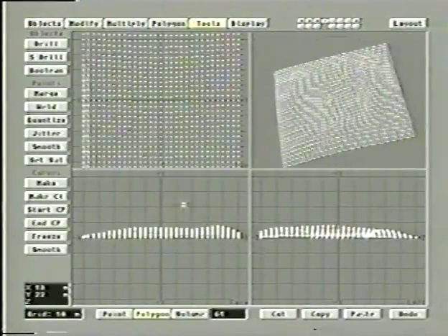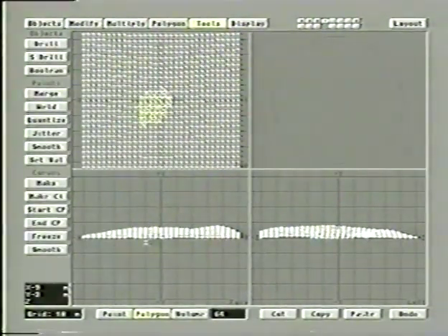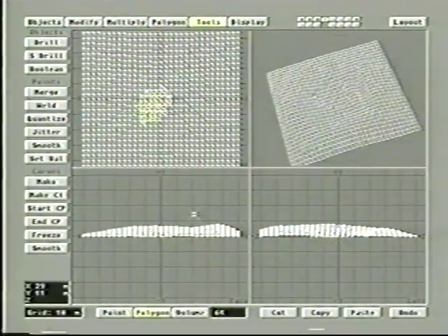By putting the ground at -1 millimeter, when the road object loads in, it will be right on top of the ground, which is quite handy because it means I don't have to push it up or anything like that. So that's all I'm doing here is putting it 1 millimeter below, so when I load in other things like houses or roads, it'll work properly. So we set it to there, hit OK, and it forces these middle polygons here to be perfectly flat. Forces them right here in the middle.